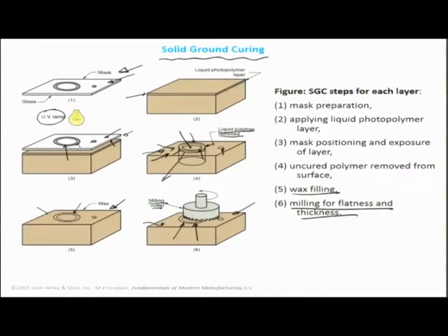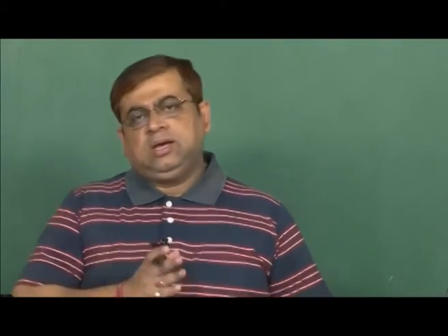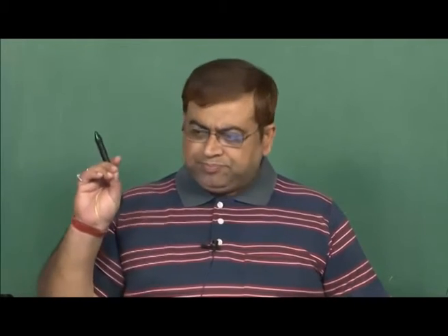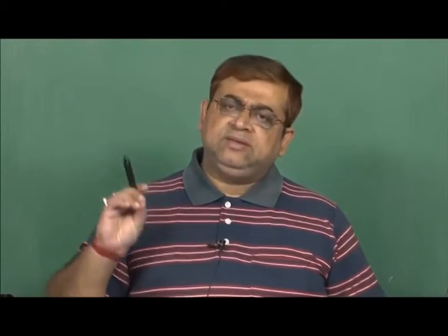It is another form where liquid prepolymer of photoresist nature is applied for building of parts. Okay, so you saw in step 1 how a liquid polymer would do stereolithography with a laser beam and a lot more complex optics getting into place with different depths of focus so that you can have a layer by layer build up.